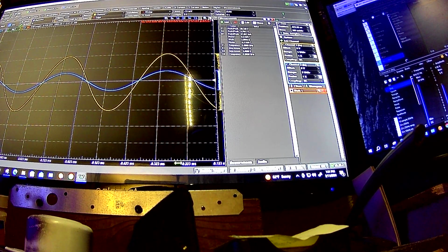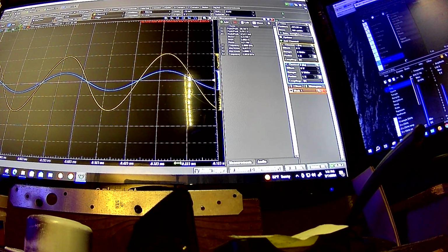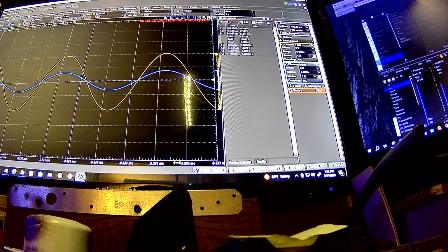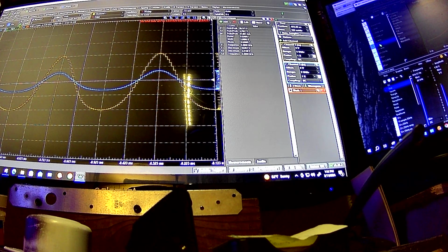But still, the filters coupled with the high resolution of a 16-bit DAC or whatnot still help work through that, because it's got plenty of resolution to spare at audio frequencies, as you're seeing here. Because a lot of signals are going to look like that, right? But they're filtered and smoothed out. The key is they can have slightly different levels for each of these plateaus you see here, so they can recreate complex frequencies with it. So, songs, that kind of thing.